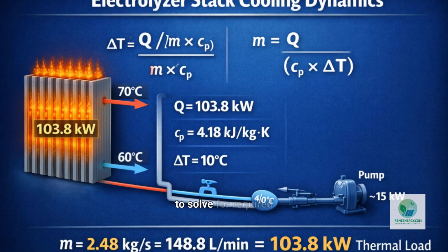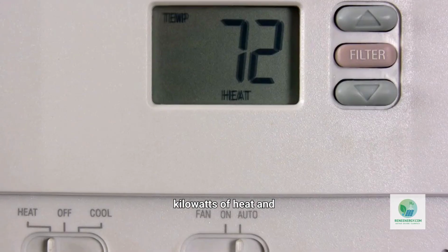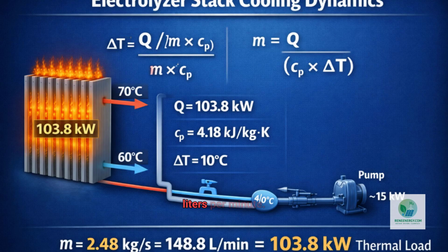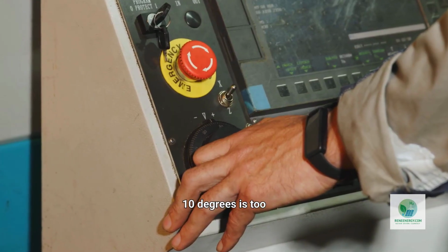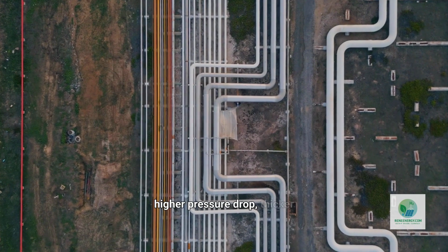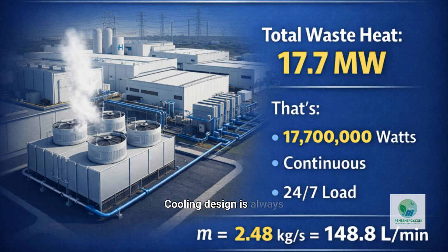We rearrange the equation to solve for required mass flow rate. If the stack generates 103.8 kilowatts of heat, and we allow a maximum coolant temperature rise of 10 degrees Celsius, the required mass flow rate becomes 2.48 kilograms per second. That is about 148.8 liters per minute. Now pause and think about that. If you decide that 10 degrees is too much variation and you want tighter thermal control, say 5 degrees, your required flow rate doubles. That means larger pumps, higher pressure drop, thicker piping, and more parasitic electricity consumption. Cooling design is always a trade-off between thermal uniformity and energy efficiency.